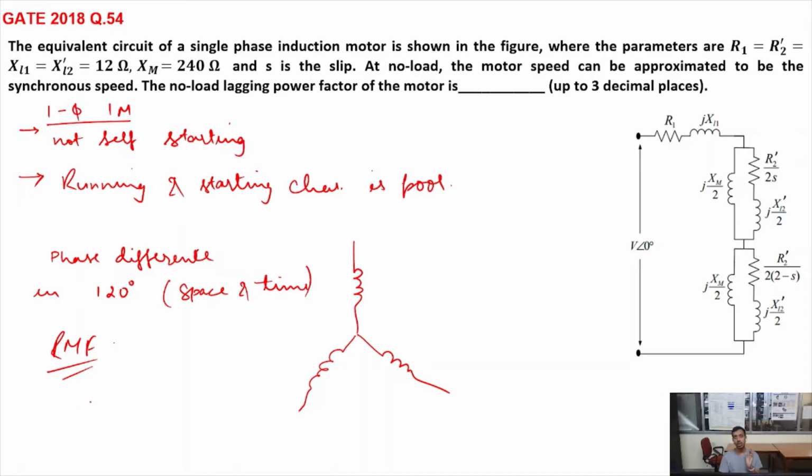Generally in a two-phase machine, both the phases are displaced in space and time with respect to 90 degree of each other. Then it can also create a revolving field. So that is the purpose. We want to break a single phase winding into two components where there will be certain displacement in phase as well as time. So let us move ahead.